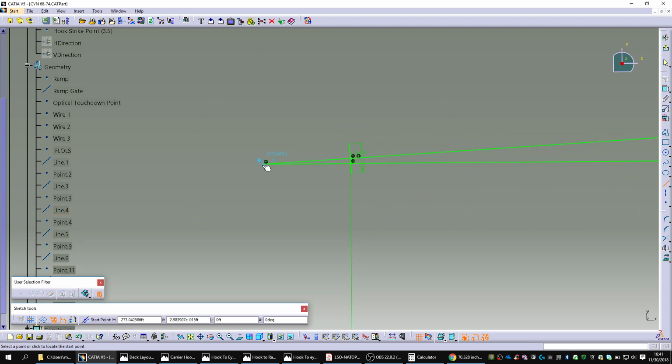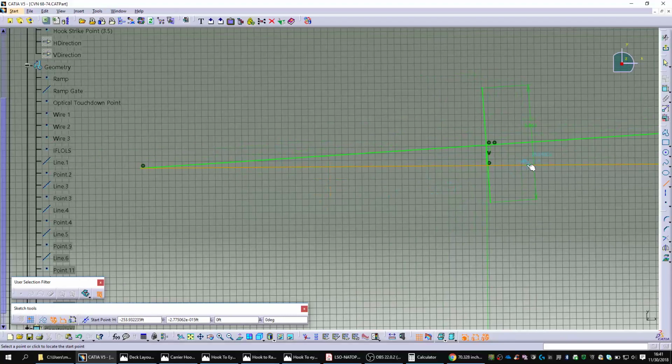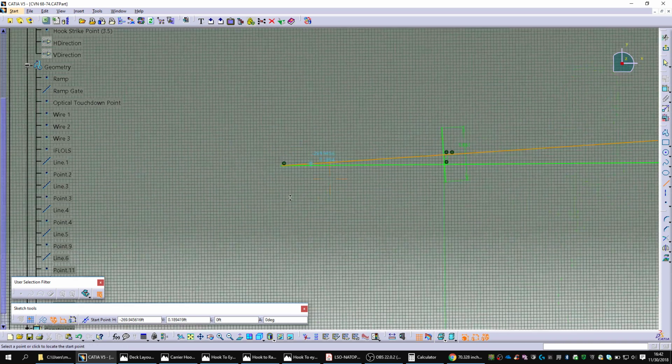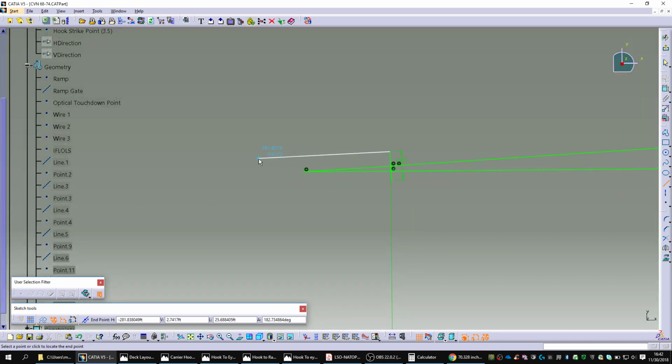Now you can do the math on it, so certainly because we know these proportions, and I've done this on paper, it's boring to watch on paper. It's much more fun to watch this. I know this height, and I know this angle here. I can know this slant distance, and I can back calculate based on the relationship of this height, which is half of that, and the angle that I have, 0.85. I know the focal point is going to be way back here somewhere. Let's see if we can draw it, though. I'm going to put in an arbitrary, there we go, something. It's picking up the extension of my center line, so I'm going to click there.